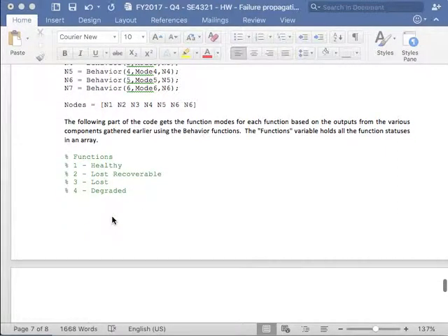And a real quick note on loss recoverable: that didn't actually show up in the slides earlier, but it's essentially a 4th state which represents if a component doesn't have the opportunity to work, we would call it loss recoverable. Think about an example like an emergency brake. If you go to use your emergency brake and it's failed, you only know when you use it. But prior to that, if it has no input, it has no chance to tell you it's failed or working. It could be either way. It's not being tested, not being demanded in any way. So that's considered to be loss recoverable.